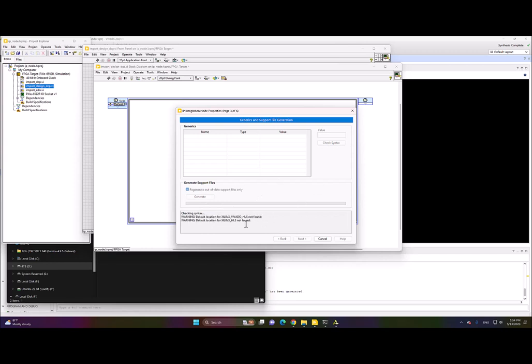If you ever get the error message that occurred here, sometimes you have to click check syntax twice. I see elaboration is running, so I think it's going to succeed. Yes, it did. Now we're clicking generate IP.